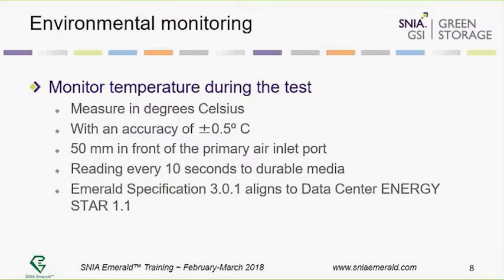Environmental monitoring is required by both Energy Star and our specification: you need a temperature sensor 50 millimeters in front of the primary outlet, reading every 10 seconds, with an accuracy within half a degree. This is 3.1 of our ML specification, and it now matches Energy Star.